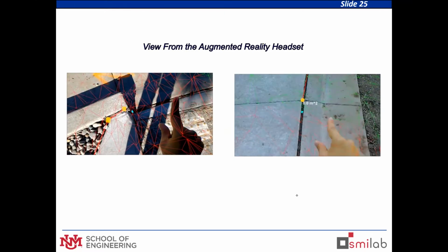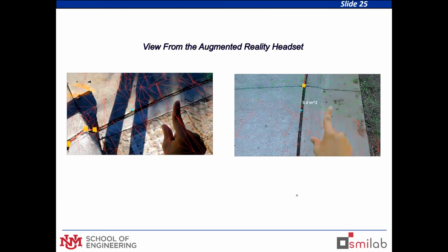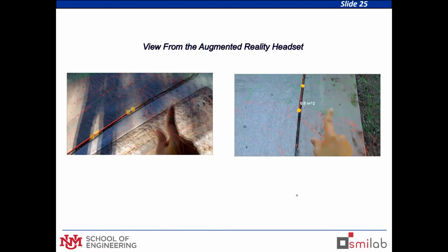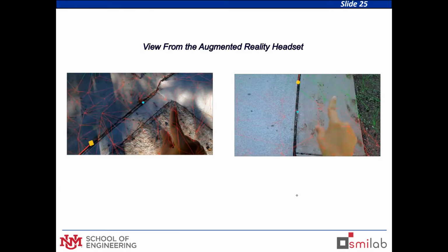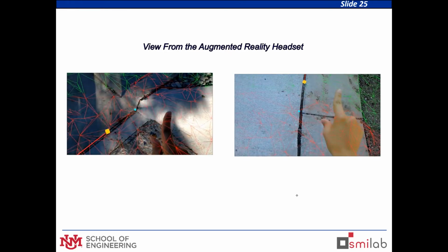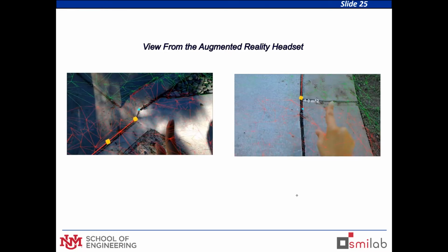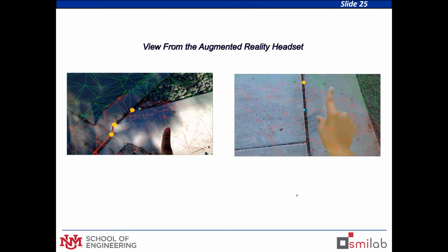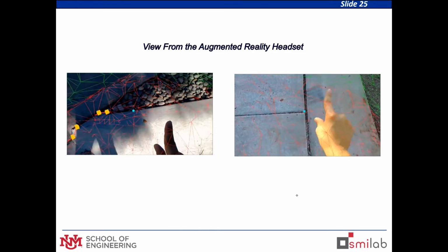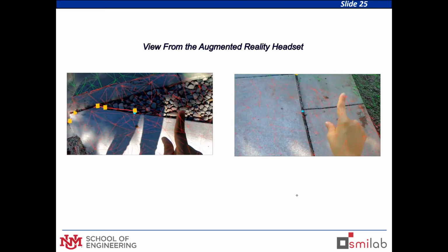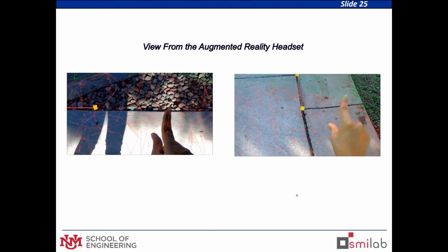And as you can see, you just walk around and select the points, X and Y. The computer is creating this 3D mesh of data that you can use for your area calculation. It takes basically a couple of minutes. I will continue, but you can see it's a very straightforward data acquisition. The point is, it's an irregular shape, otherwise you would need a total station to get your X and Ys.